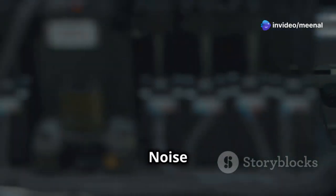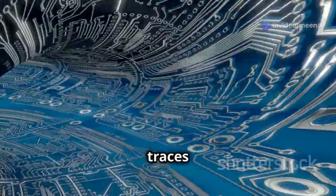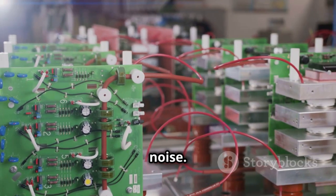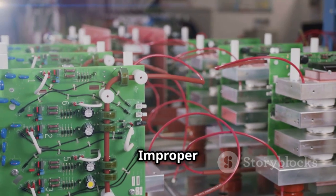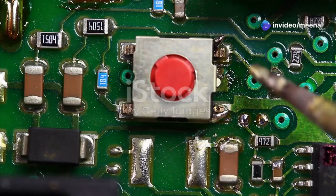Pitfall 2. Noise and interference on the reset signal. Minimize noise by keeping reset signal traces short and direct. Use ground planes and decoupling capacitors to reduce noise. Pitfall 3. Improper grounding. Use a single-point grounding scheme to avoid ground loops.